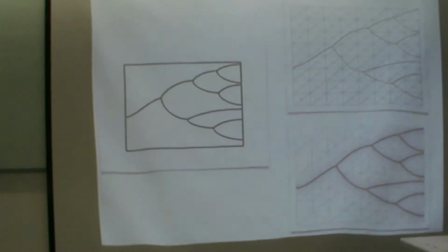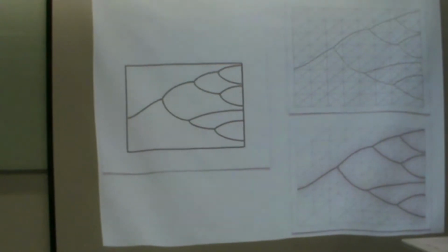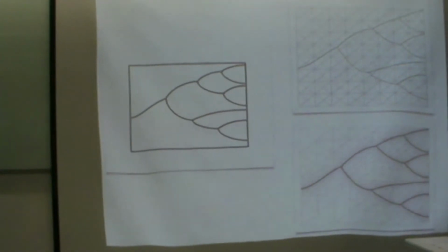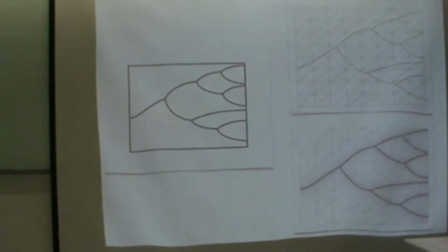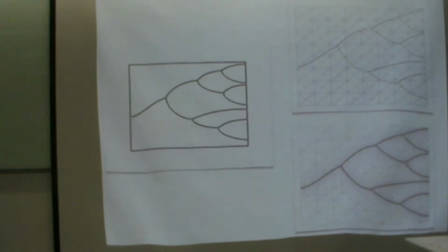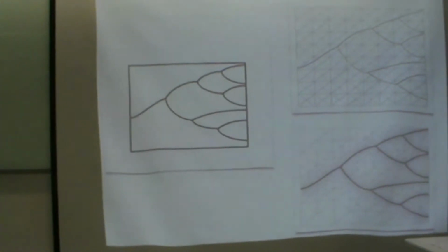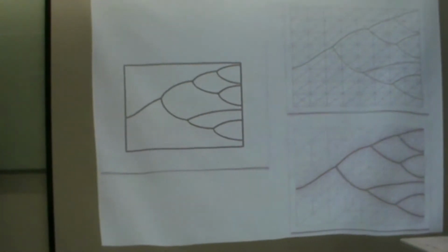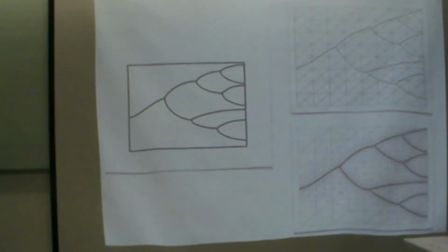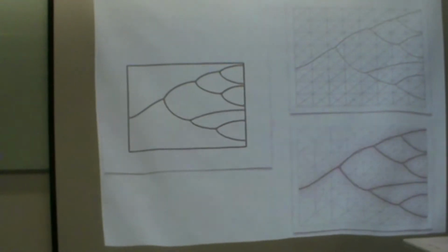And of course, now we can do more complex things, like branching cracks. No problem at all. If you do this with the cut finite element method, you have to consider that you have branching points, and you could have several branching points. So you have to implement this now with elements that have several copies, which of course complicates things. It's not undoable. We're doing it right now, but this is much easier.